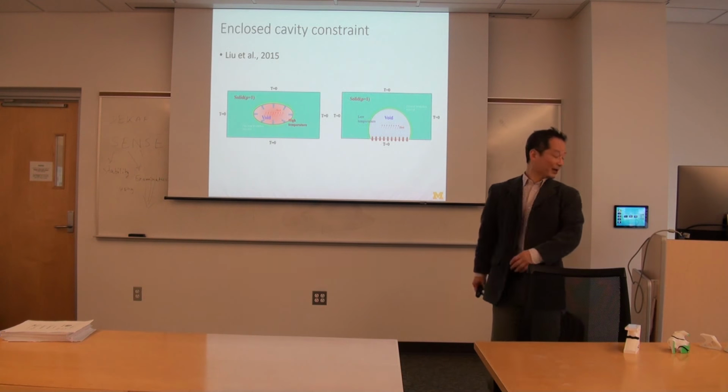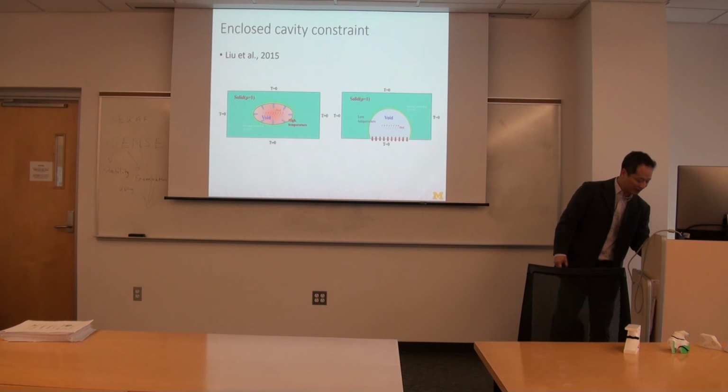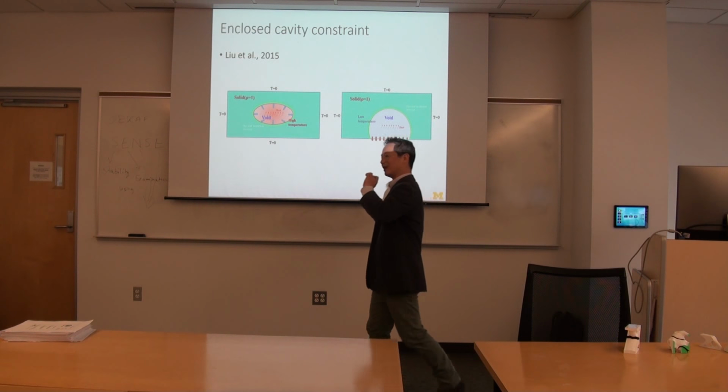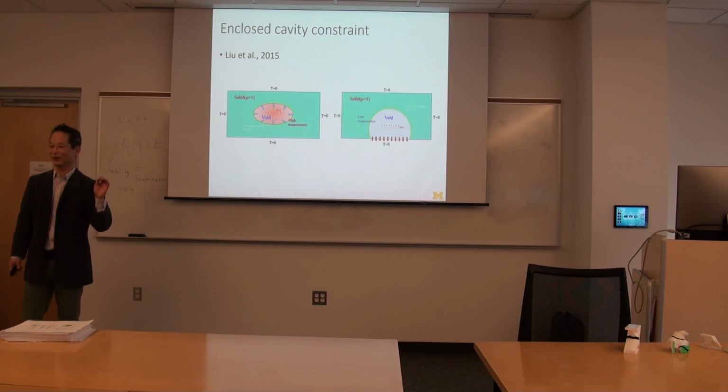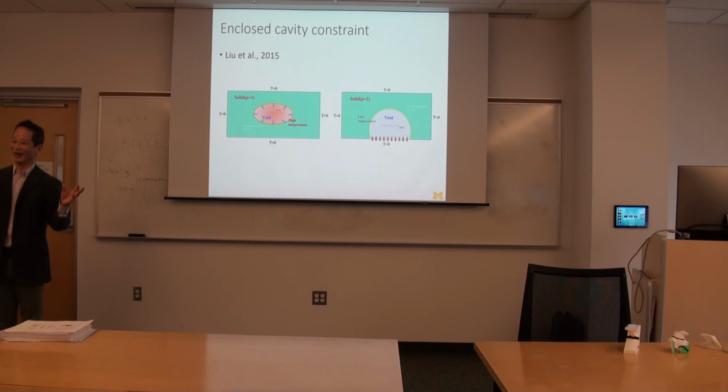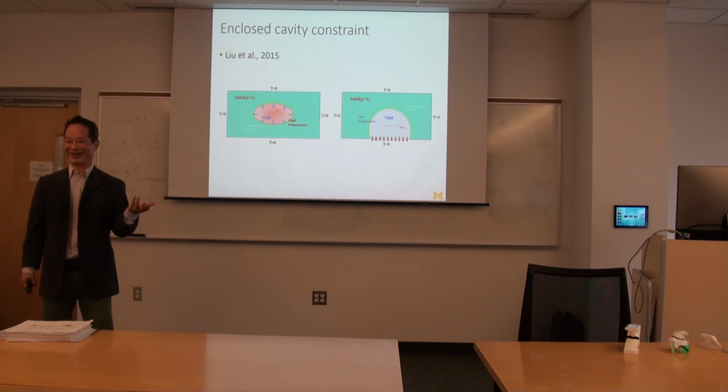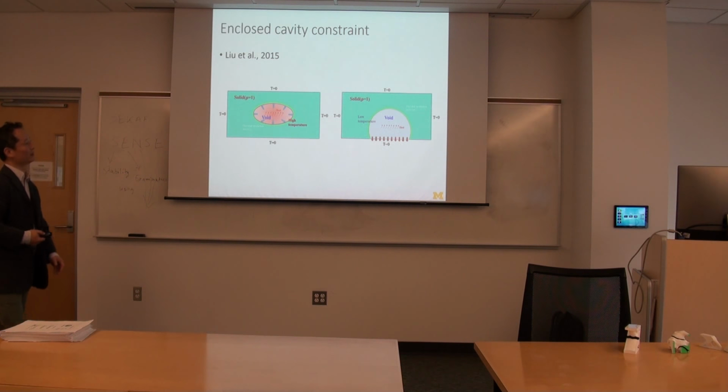And somewhat independent of undercuts, there's a method which strictly tries to eliminate holes. Now, completely enclosed cavities or holes are also common constraints on many manufacturing processes, if you think about it. Even for additive, you cannot really have completely closed holes, especially for the powder bed process, because where would the powder escape? Not to mention you cannot do that for casting either. So this is a common constraint for many processes. And again, we didn't invent it.